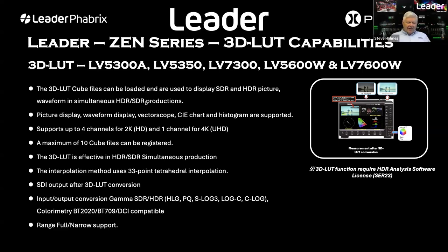Yes. And as Kevin said, in using this in a IP environment in 2110, we will give you a SDI output to drive your monitors. So if you're taking log in and you want a PQ output, you get your PQ output and you can actually run that to your HDR monitor right off the 2110, straight out of the scope. And finally, it supports both full and narrow range video. But of course.